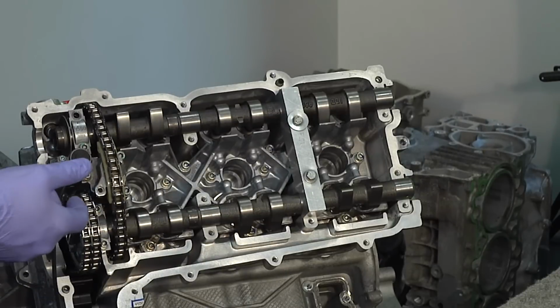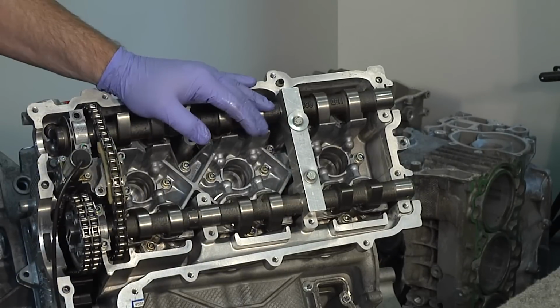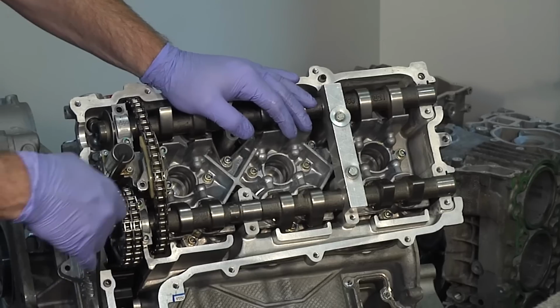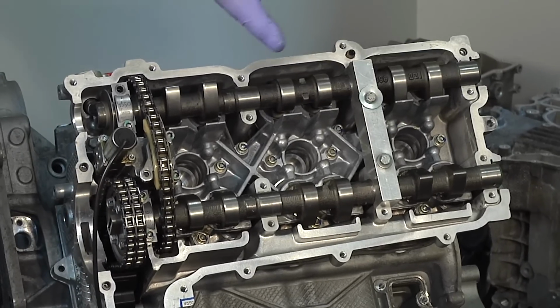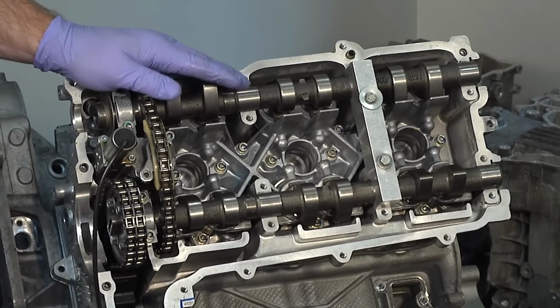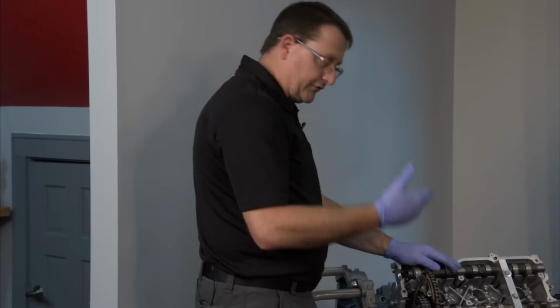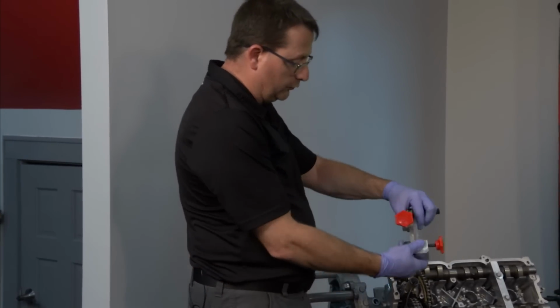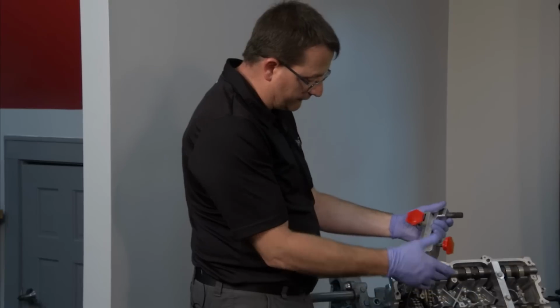Then we're going to set that aside. At this point in time, we would go ahead and put our camshaft caps back on. We would tighten the bridge back up, get that in place, and then we're going to go through a scenario of the camshaft timing, which uses this particular tool here that also comes in the kit from Baum.